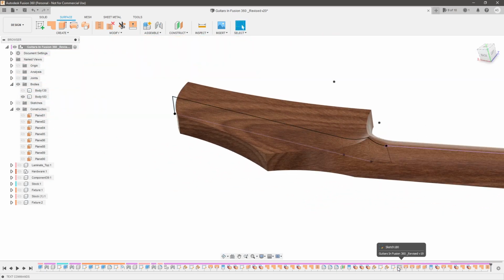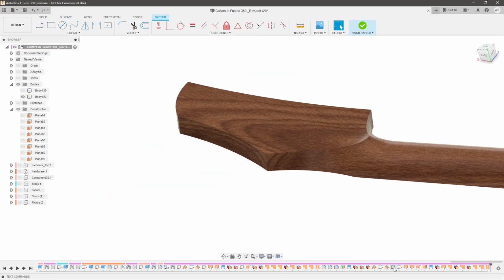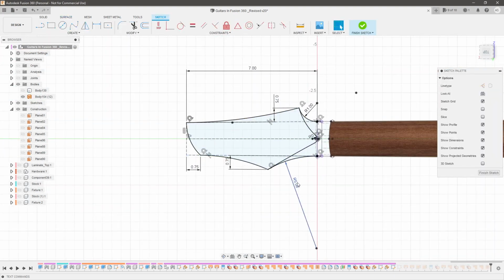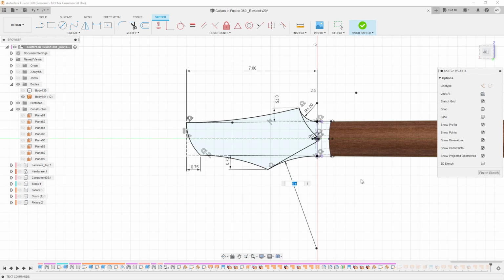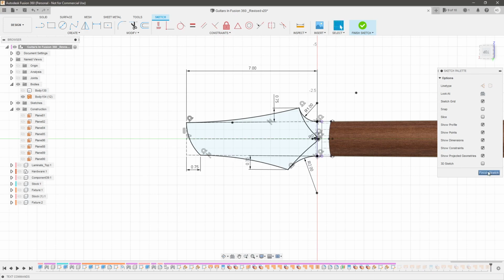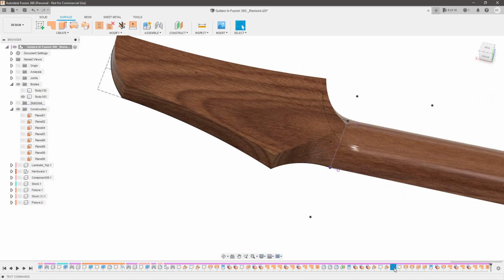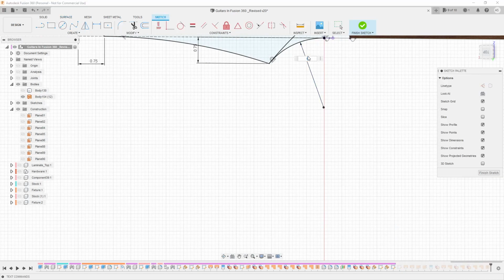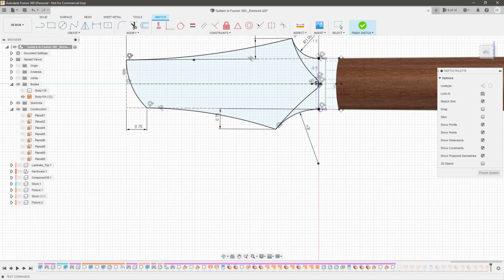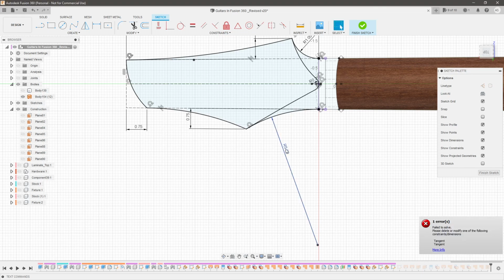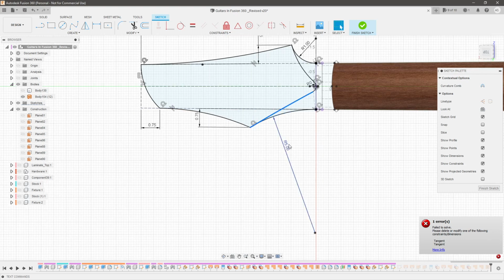Another thing we can also check, wrong sketch, we can also check these volute arcs. So let's try changing the radius of this and make it smaller. Let's go like 2 inches. And we still have a perfect transition. Let's go back and make it like 6 inches, or let's go to 5. Let's try 6. Now it won't let me do that because at 6 inches, this line will end up being a perfectly straight line and needs to remain an arc. So I guess that is one limitation of this, there's a theoretical limit to how far that arc can come out before this turns straight.